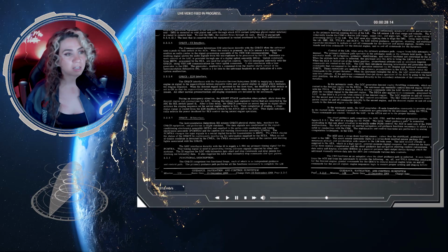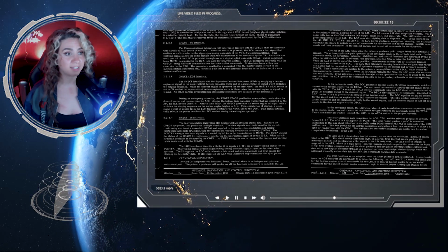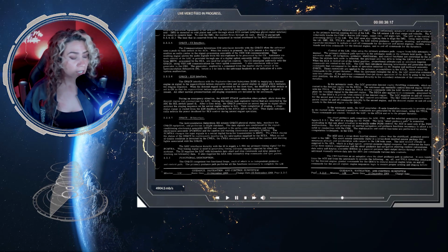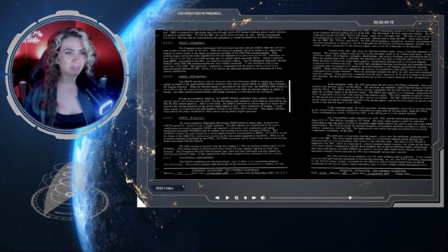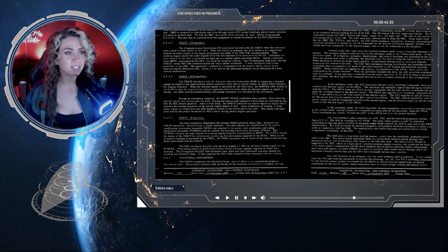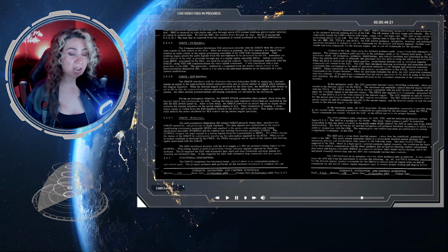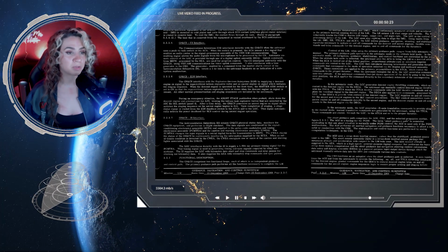In the automatic mode, the LGC generates plus x-axis translation commands to provide ullage. In the manual mode, manual translation commands are generated by the astronaut using the TTCA. These commands are routed through the LGC to the ATCA and onto the proper thruster.